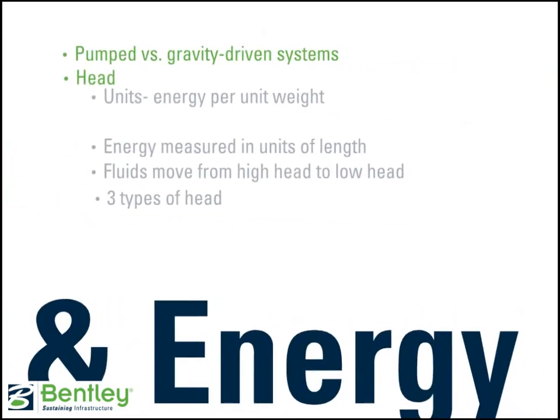Another hydraulic consideration is the energy within the system. When the flow in a network is driven by a pump, the designer has some degree of control over how much and where energy is injected into a network. On the other hand, gravity-driven water networks don't have an outside source from which energy is applied. This is the distinguishing characteristic of gravity-fed rural systems, and the challenge there is to effectively manage the conversion of pressure energy.